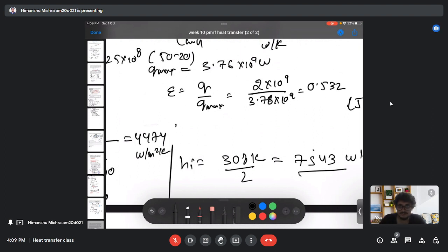And for the cross flow heat exchanger, we will be using the graph. From the graph, we can directly get the NTU as 0.759. To know how to use the graph, you can see the last video where I identify the value of NTU from the effectiveness versus NTU plot for the cross flow heat exchanger. I also described where to use a correlation and where not to use a correlation.